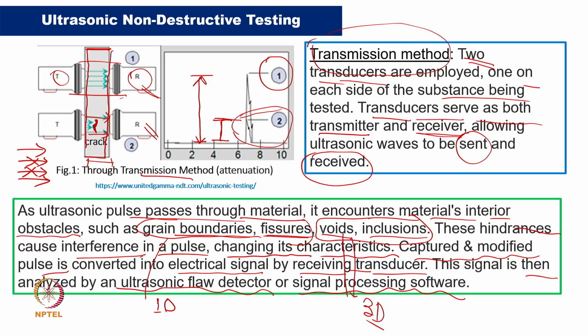So, we really require signal processing software, or what we call some sort of ultrasonic flaw detector. These are the essential points. However, many times we do not really consider this, the reason being we buy some equipment, directly put it on our machine, and we get some sort of results. As mentioned earlier, if we really require valid or good results, we need to do good calibration